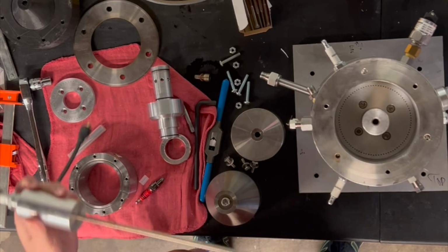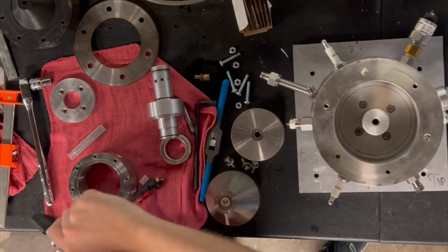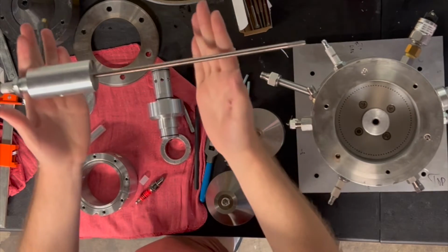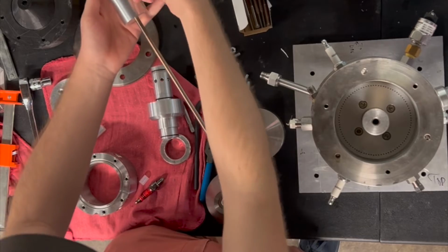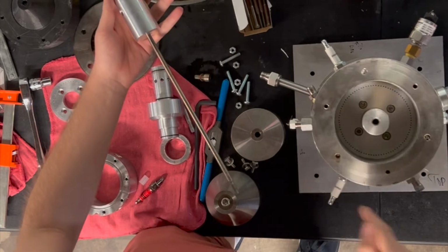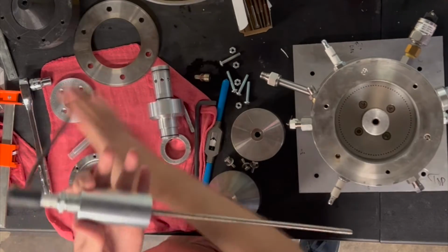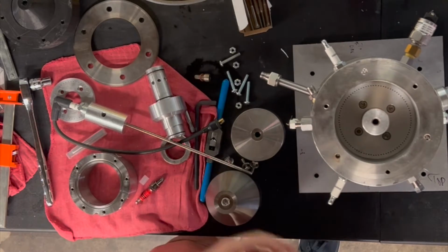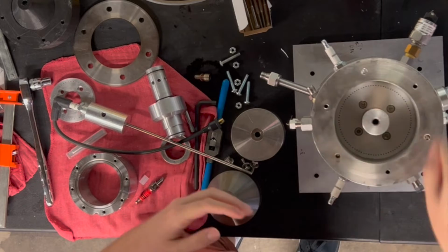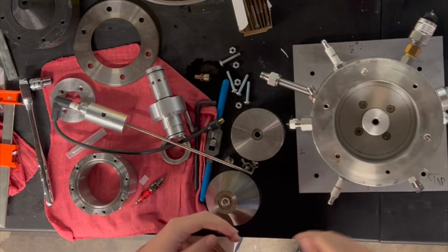And then we've also got this input port right there, which is very important because that's where this goes. This is our detonation igniter. It basically forms a detonation wave that propagates along this tube and enters the chamber to begin circulating around. Now, the way this engine works is just like any other rotating detonation engine. You have a spinning rotating detonation wave around the outside.